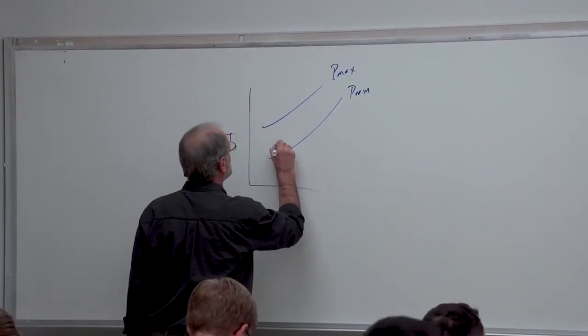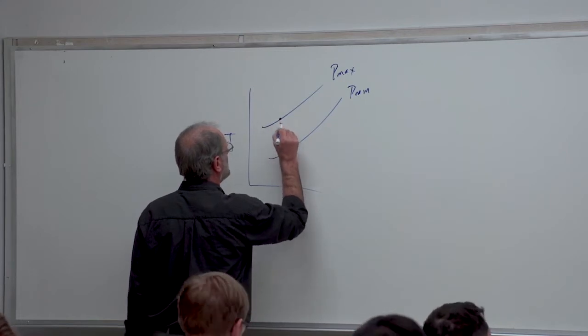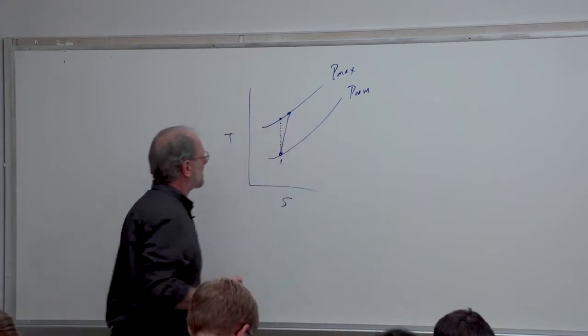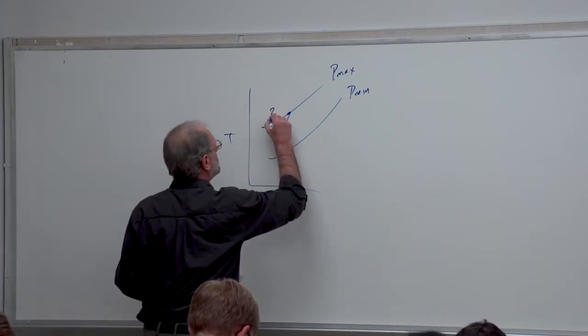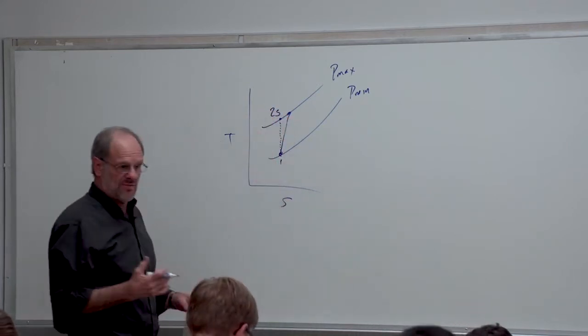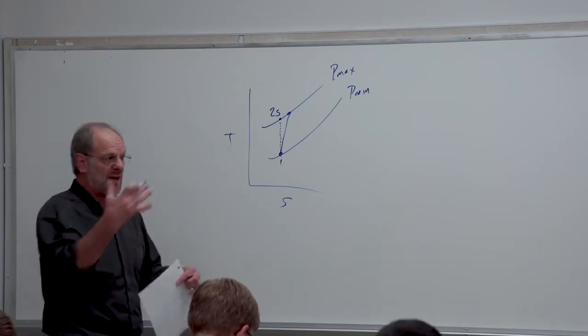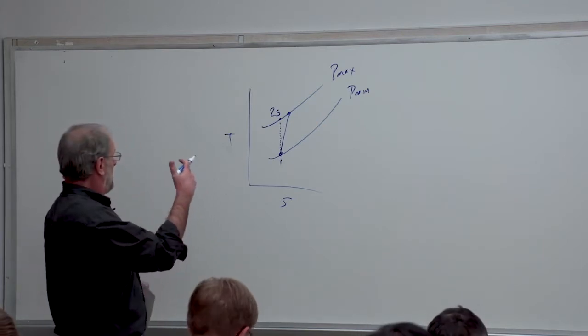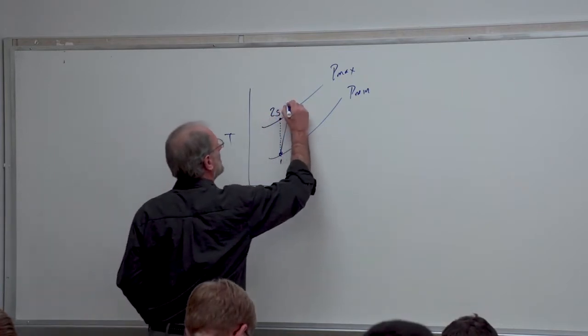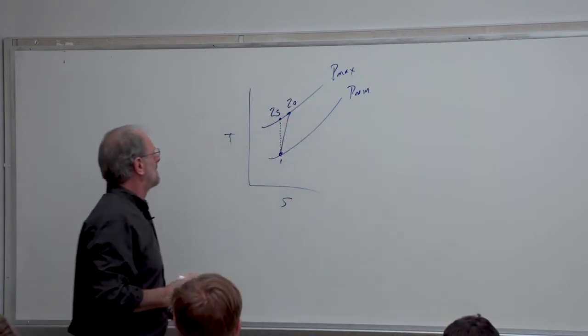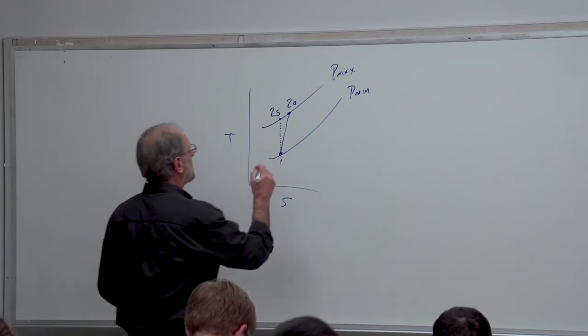We know that since we're given isentropic efficiencies, we have to recognize that we're not only finding the assumed ideal exit conditions from the compressor, which would be point 2s, but we have to use the isentropic efficiency along with point 2s data to get the conditions at point 2 actual. So let's show both of those on this diagram.